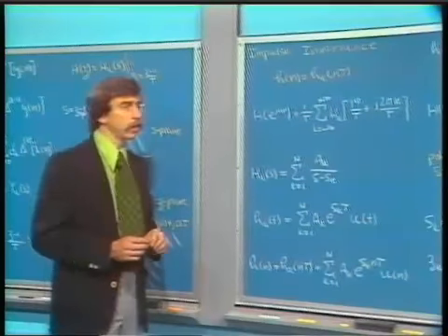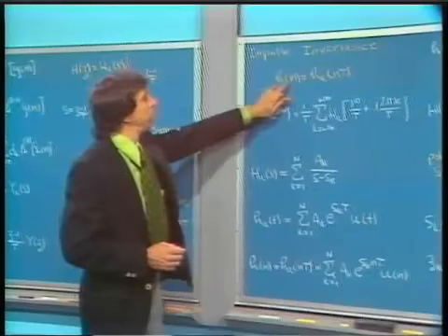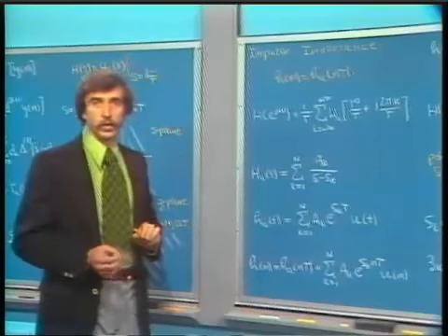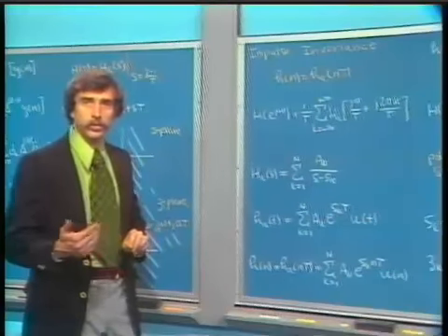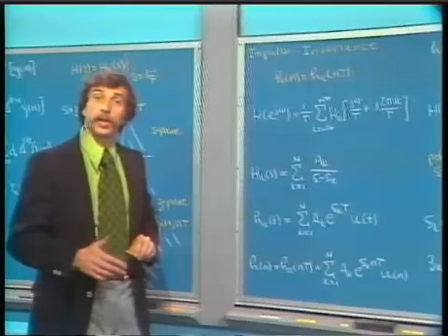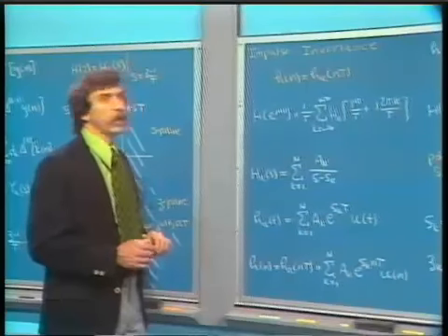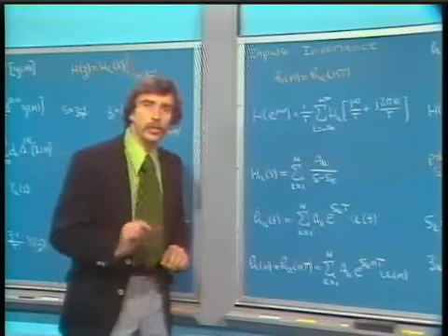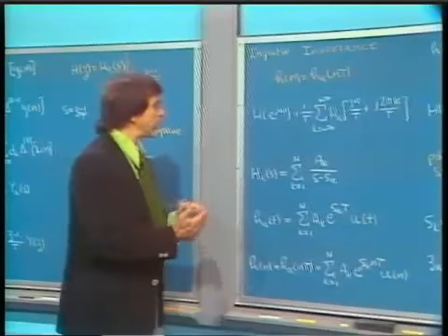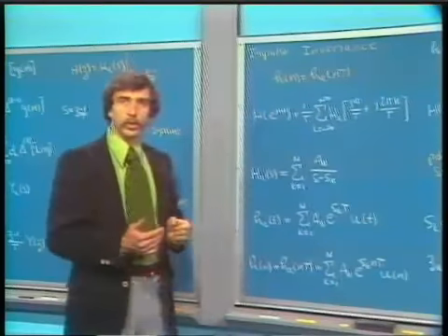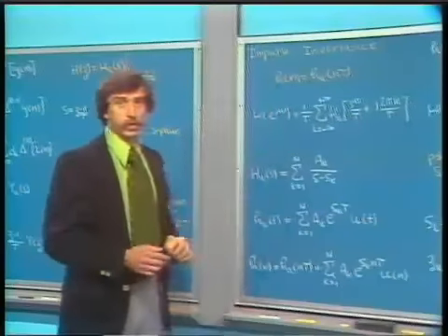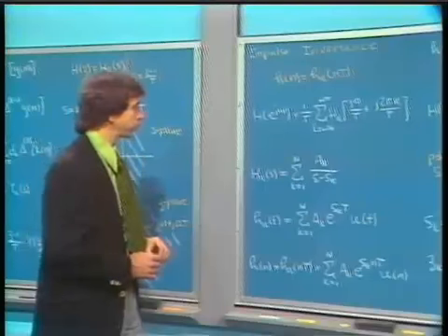It should be pointed out, incidentally, that impulse invariance doesn't imply step invariance, and you'll see this in the problems that you work through in the study guide. Impulse invariance does not imply step invariance, so that, in fact, if it was the step response characteristics that we wanted to preserve, then the technique here isn't what we would use. We would use a modified technique, which would be not impulse invariance, but step invariance.